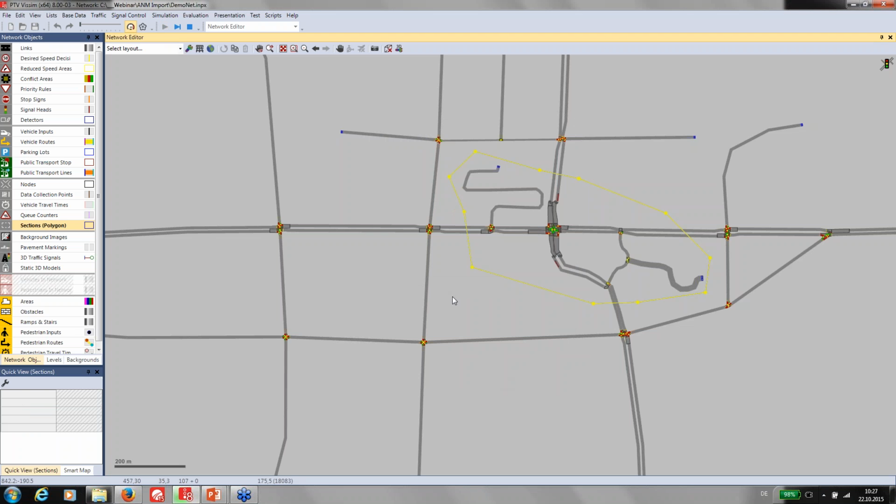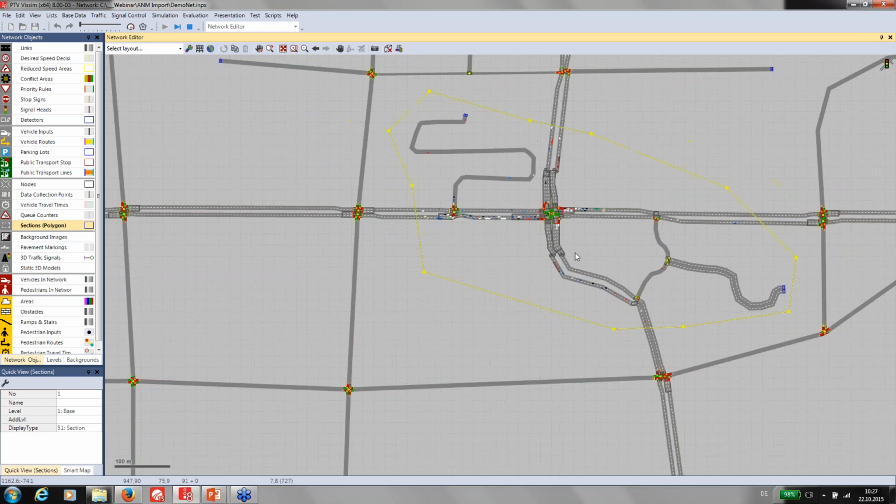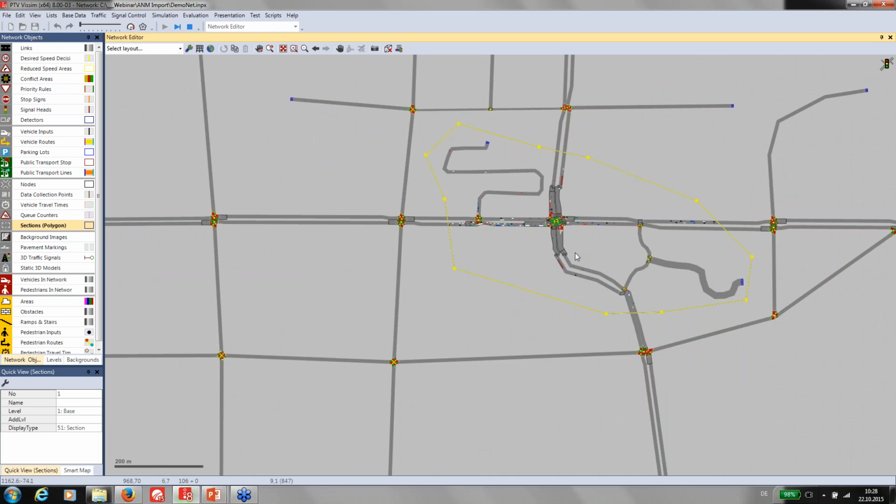So at the moment we are still in the quick mode. You will not see any vehicles, but if I switch that off, you can see the vehicles in the microscopically simulated area. And as we have also noted, you can use the same path file produced before for the dynamic assignment. You can, of course, have several of these sections in your model. And of course, there's also an impact on the runtime. Microscopically simulated areas will slow down the runtime.